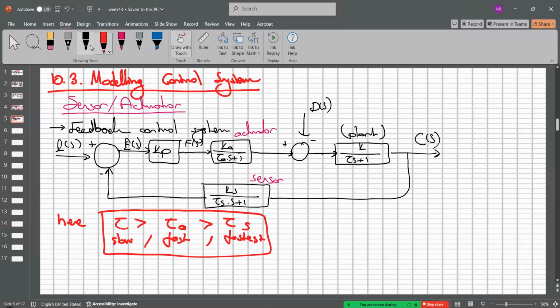And so how can we obtain this value? This directly relates to the response time. This response time can be obtained with the actuator catalog value or sensor catalog value. Since we want to control the system, the sensor and actuator must be faster than the plant, especially for the root locations affecting the oscillation or the root divergence.